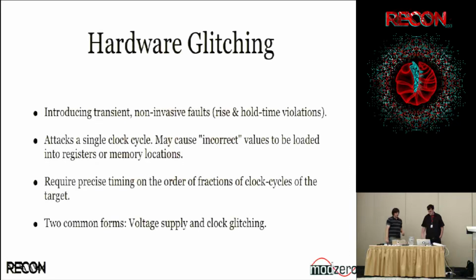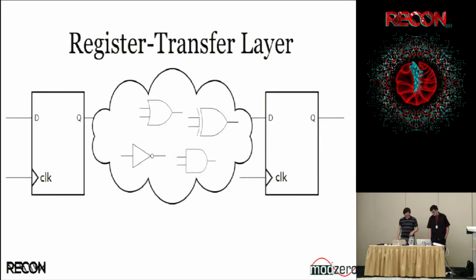So glitching, you can think of it like this. The technical term is register transfer level. In modern chips, you basically have registers, and you can think of it as everything starts in a register during a clock cycle, and it ends up in a register. So now we can either play around with the period, the amount of time that the signals have to propagate from one register to the next, or we can play around with the voltage. And there we can do a couple more things.